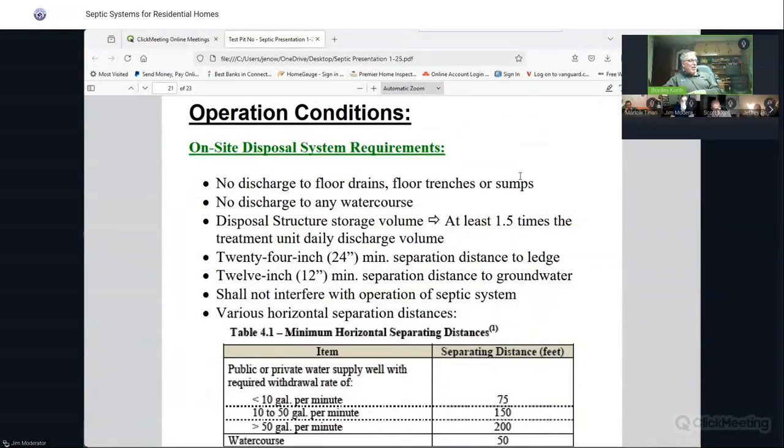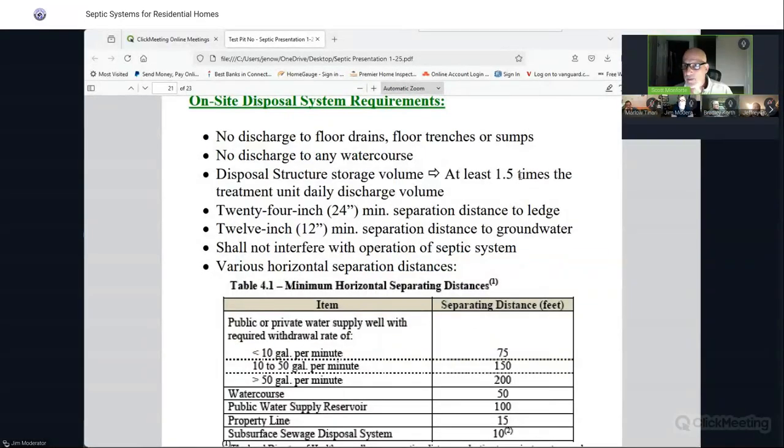Now, I was talking to a well contractor I know, and he told me that neutralizers are okay in a septic system, but not softeners. Is that correct? Yes, that's correct. Calcite systems are exempt from this regulation. A neutralizer would be a calcite type system. It's limestone. It's the salt that's probably the big thing, and any other treatment chemicals you're putting in. So you don't have to do it if all you have is a neutralizer, but if you have a water softener, you have to do this.